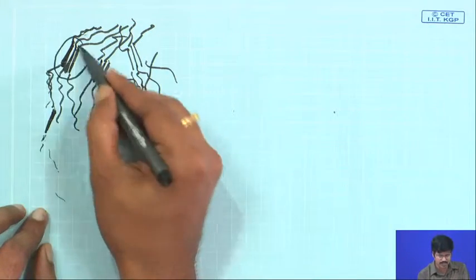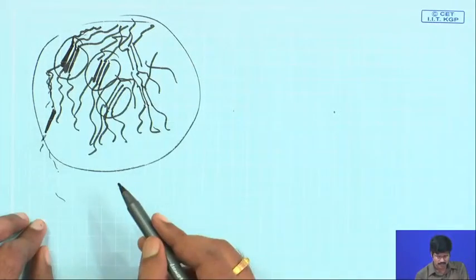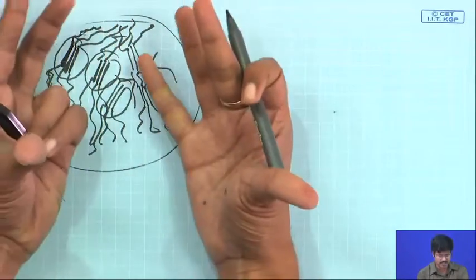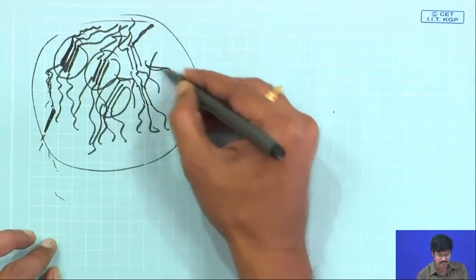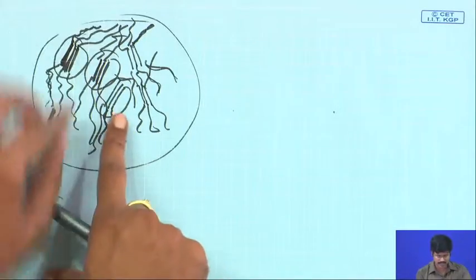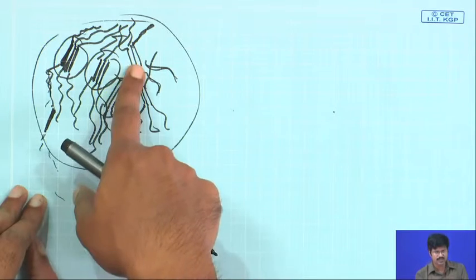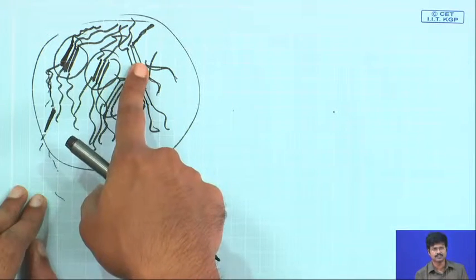So, they basically provide 3D cross-link centers for the whole system, and these cross-links are present in the material, which will have what you call a soft matrix, made of these flexible chains, which are basically your polyester part, all right. So, obviously, these cross links will give you the stiffness of the material, and this will also give you the tensile strength of the material.